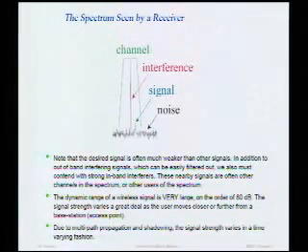In a wireless system, for instance, we have multipath propagation. Now, multipath propagation means that if I'm communicating with, let's say, the base station, which is at the end of the room, there's many paths between me and the base station. There's a direct line of sight path, there's a path that would reflect off of the roof, there's a path that would reflect off the ground, there's a path that reflects off that window there, and so on and so forth. And so I'm not receiving just one signal, I'm receiving an ensemble of signals.